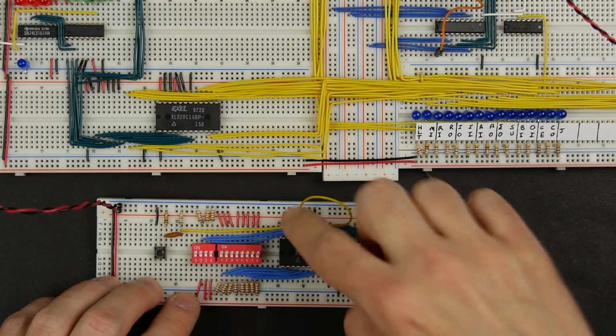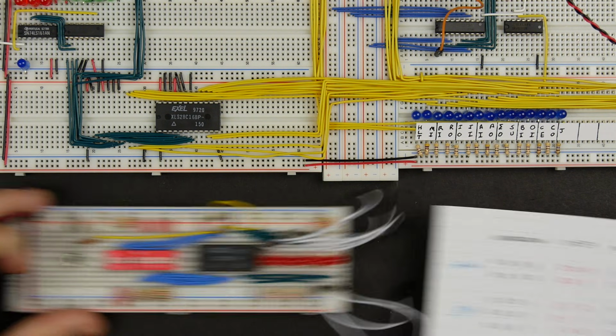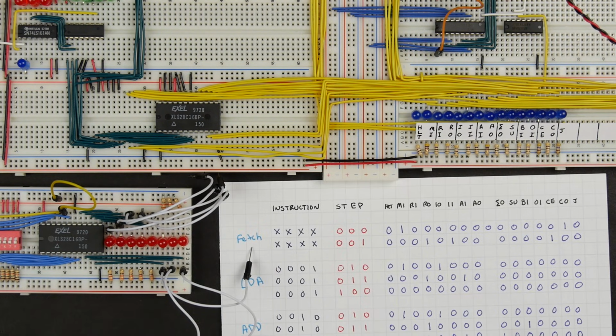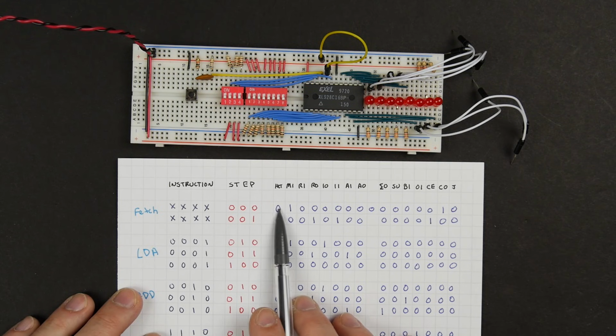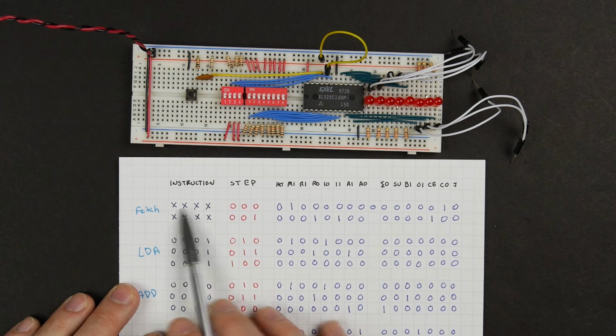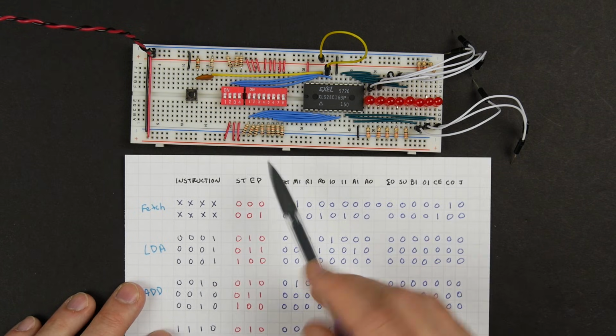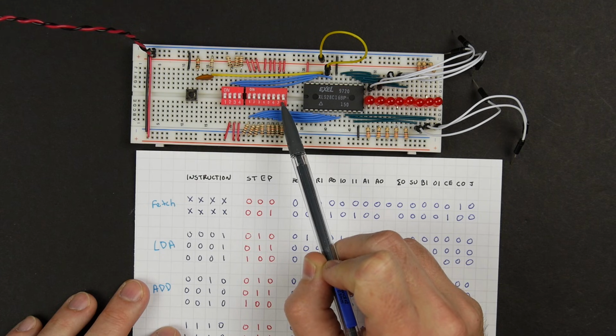So I go into write mode here, and basically what we want to do is write in this data. Essentially in each of these addresses, we want to write the appropriate data, this here. So this is the EEPROM on the left that we're programming now. So the first thing I want to do is program in for step 0. And so step 0 is where these first 3 bits of the address on the left are all 0, 0, 0, 0.